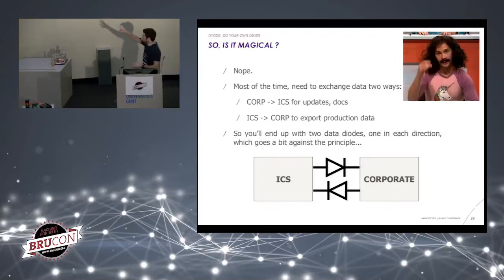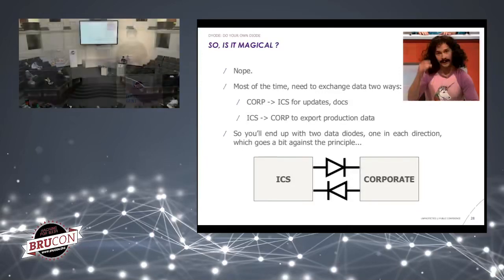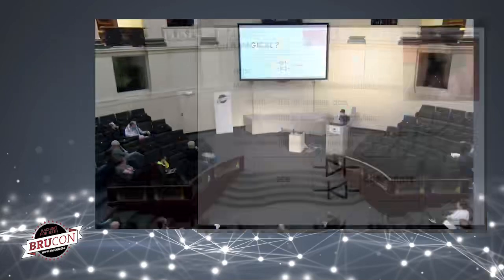So you have to be careful, because using a data diode, if you have just the same connection at another network point that is two-way, that doesn't seem right. So it's not for everyone, it's not for all the processes, it's for very specific use cases, and you will not be able to use data diodes everywhere. That's just what I wanted to say with this slide.